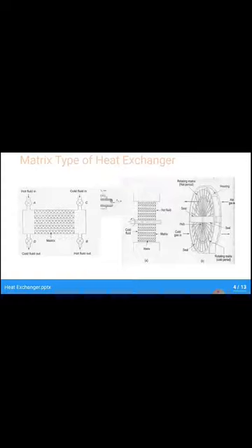Now our matrix has the energy inside it, so we close tap A and tap B and open the cold fluid tap C. Cold fluid comes inside the heat exchanger and collects the energy from the matrix while flowing out through tap D. This also happens for 1 minute.